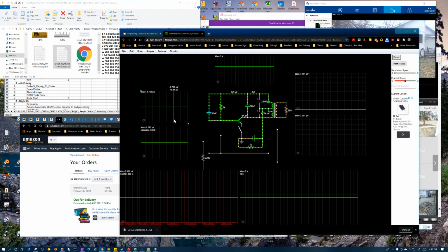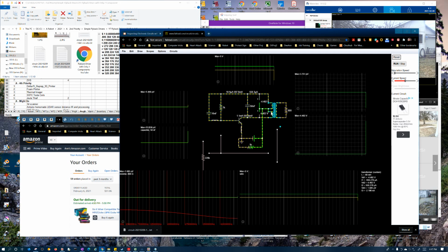Okay, yeah, I'm running a simulation on... You can see this circuit here, basically. I got this set up so that I could establish transient conditions. Right now, the thing's turned off. You don't need this anymore, really, because I zeroed the capacitor's voltage at startup. But anyway, if we go ahead and turn this on, we can kind of see how this oscillator builds up.